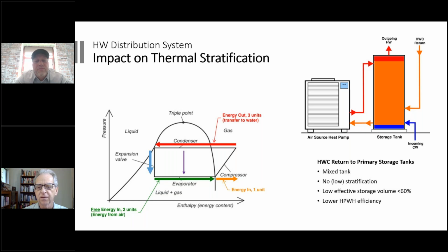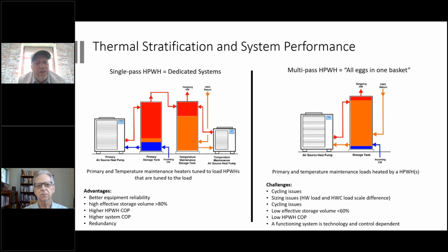And would you also recommend that rather than one giant heat pump water heater, they have a couple of medium-sized ones? No, absolutely. And I think on the reliability and redundancy plan for your heat pump, I would recommend you at least do 2 heat pumps at a minimum. So instead of 1 10-ton, you do 2 5s as an example. It just gives you a chance that one of them is still operational, and you can meet quite a bit of load with just the one. But definitely take your reliability into account.